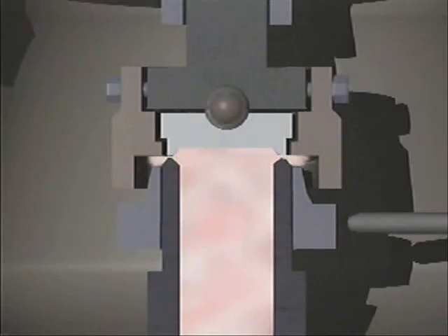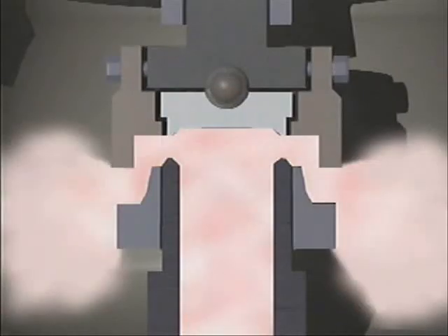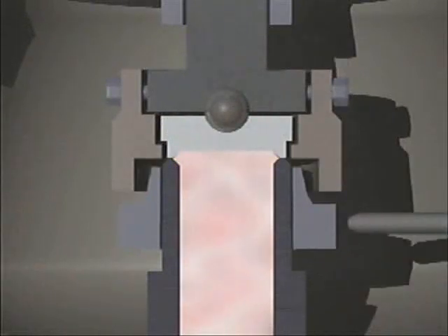While the valve briefly simmers, the flow of the fluid as it discharges outside the valve's seating area increases the lifting force. Then, the reaction hood deflects the discharging fluid downward. Creating a reactive force by deflecting the flow of the fluid further increases the lifting force and causes the valve to pop open. As system pressure returns to normal, the valve closes.